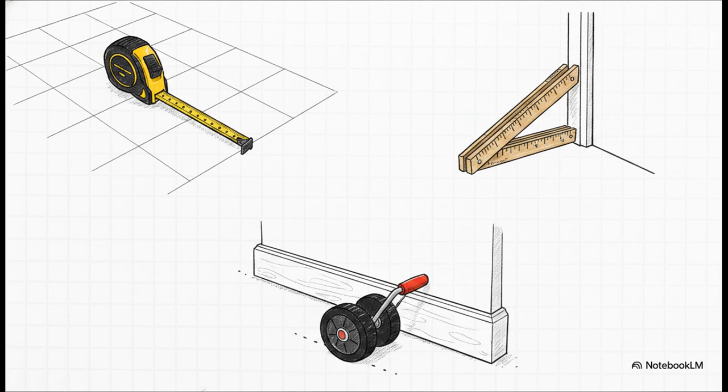If you're in solid plastering, those folding rules are absolutely brilliant for measuring window and door reveals for corner bead installations. And for all the painters listening, here's a really fantastic trick. Use measuring wheels. They quickly determine the total linear distance of skirting boards when you're pricing or planning out your trim painting. Such a game changer.